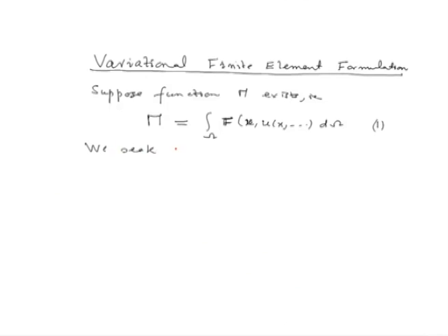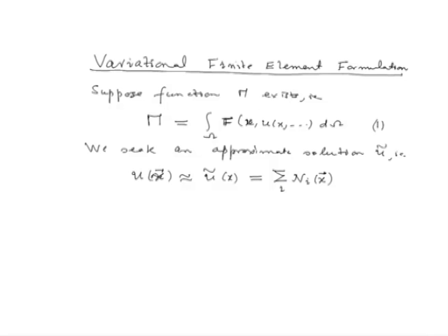Now, what we want in finite element analysis, we seek an approximate solution u tilde, that is we will approximate our u of x by u tilde of x, and this u tilde of x is defined in terms of our interpolation functions, that is N I, which depend on the spatial coordinates, and the discrete nodal values.